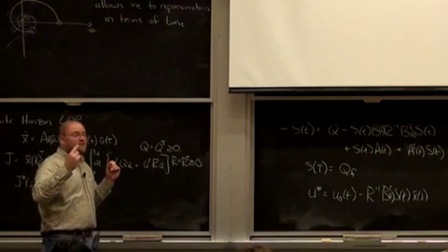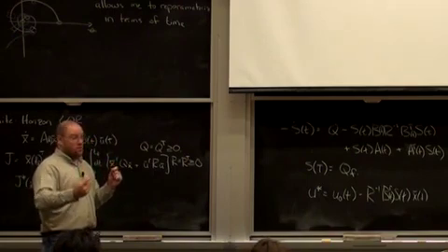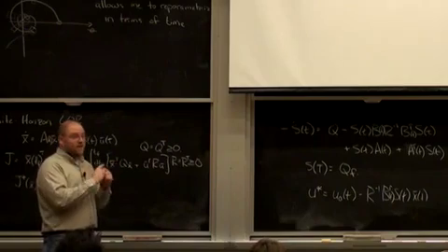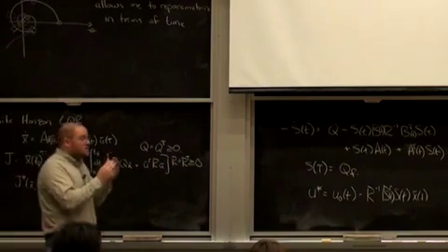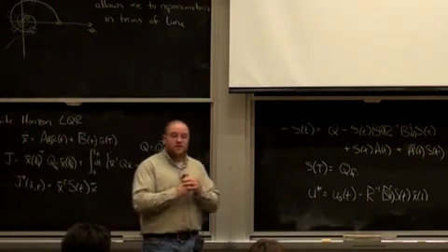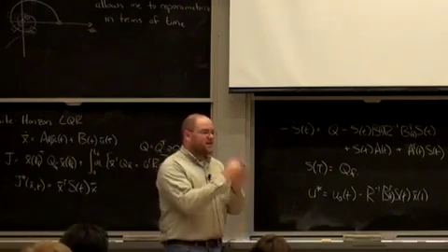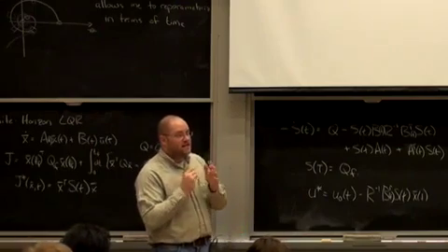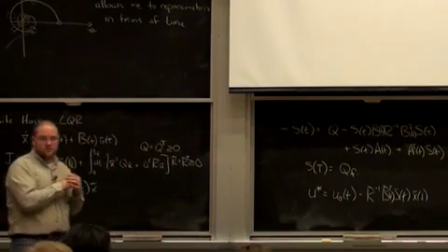The thing I haven't convinced you of yet, because I only know how to do it from showing examples, is that it really works well. So even though it's a linear approximation of the nonlinear system, something like the acrobot or the cart pole swing up, it's got a huge basin of attraction. Lots and lots of initial conditions will find their way to the trajectory and get to the goal, right?